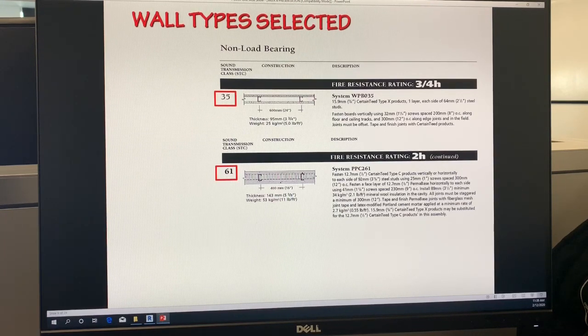Okay, so that's the big thing here. Not only the acoustic barrier inside, but also the double gypsum wallboard, 5/8 inch on both sides. Whereas this one is used within your suite. So if you've got an enclosed bedroom in your suite, you can use this one. Or if you've got a bathroom or closet in your suite, you can use this one.